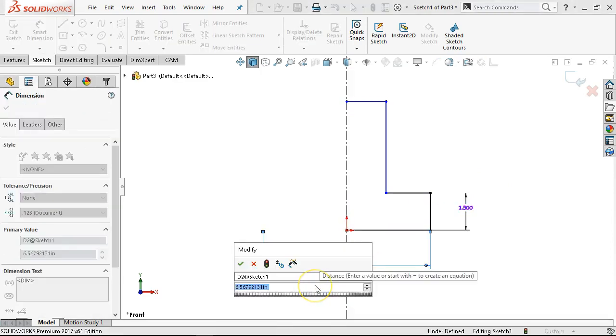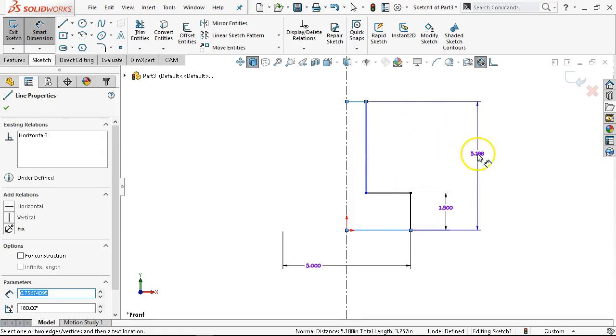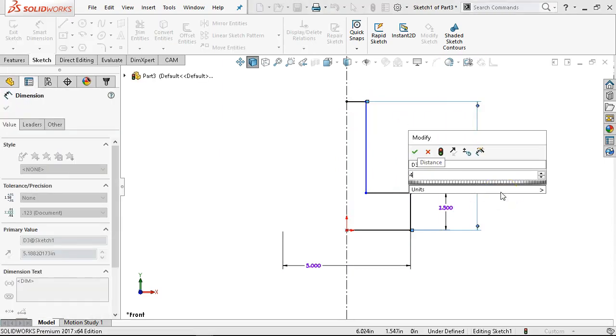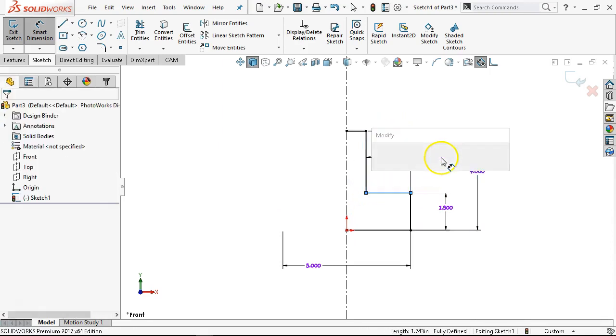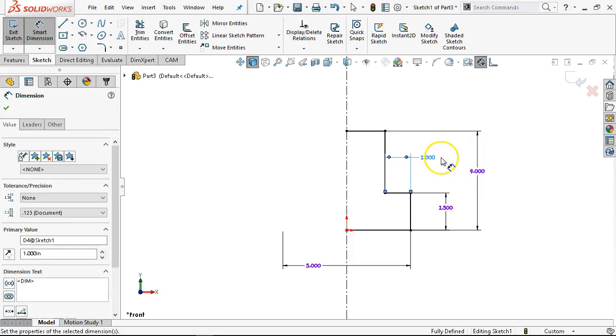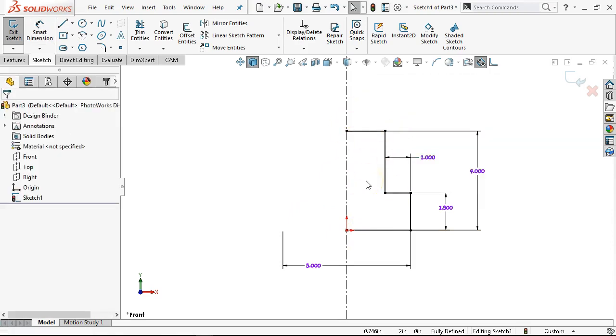So if I can get those relations out of the inferences, and we're 5 inches overall, I would rather pay attention to those little yellow boxes as they're popping up, and then pretty much just see that the geometry is being created correctly. But after I've gone through that first run through of creating my sketch, the items that I missed on, I dropped the point away from the origin, I wasn't vertical, I wasn't horizontal, I'm going to try and go through and add all of those relations that I can recognize.